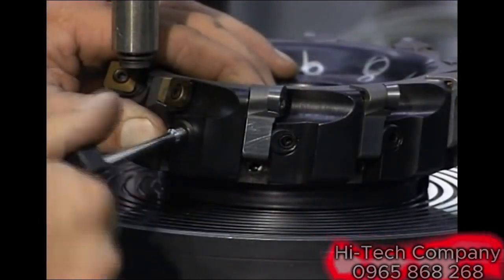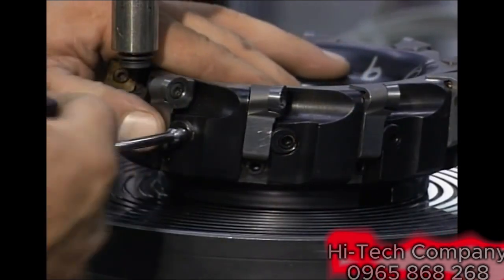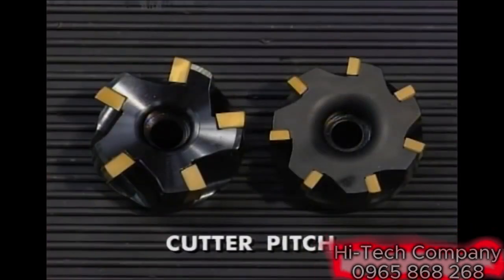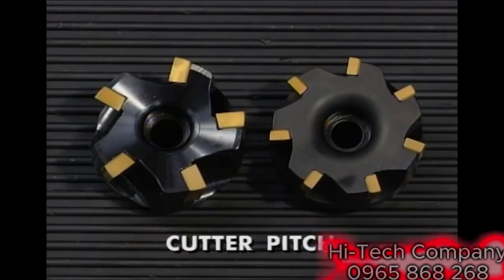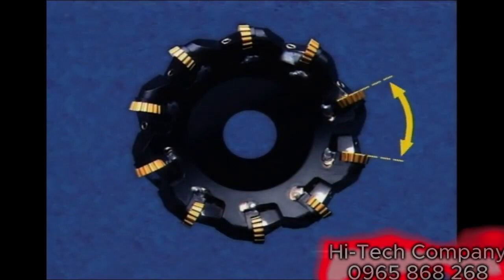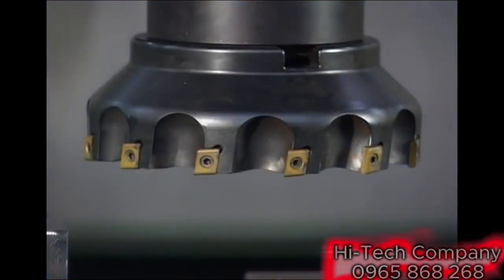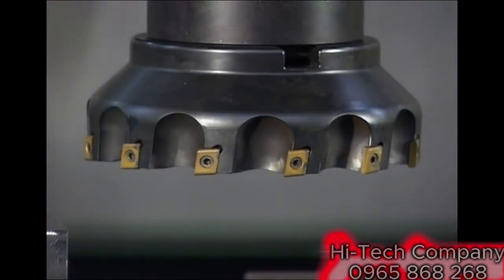This allows the orientation of the inserts to be varied using the same cutter body. The pitch of a milling cutter is determined by the number of inserts in relation to the cutter diameter and can be defined as the distance from a point on one edge to the same point on the next edge. The coarser the pitch, the larger the chip gullet.